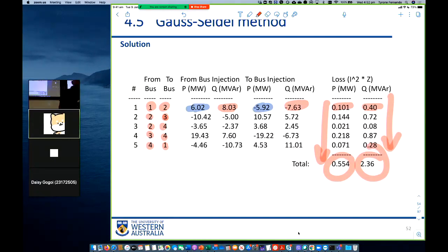We can add up all the active power consumed in each of the loads. So you can also do a double check. Active power consumption in all the loads plus the active power losses in the lines is what the generators actually generate if you sum all of them up. So do this double check. Right? So you have a bit of calculation to do at home.